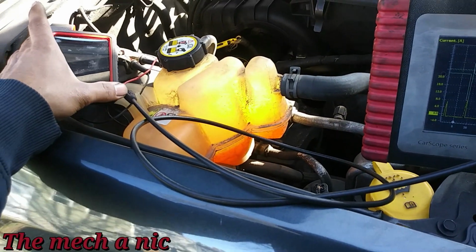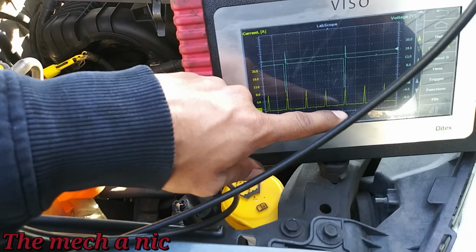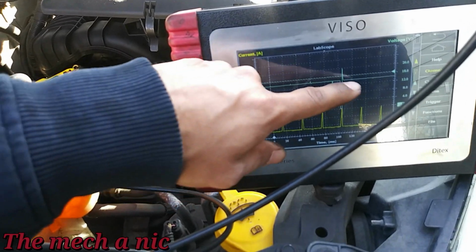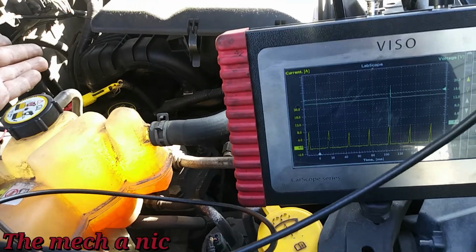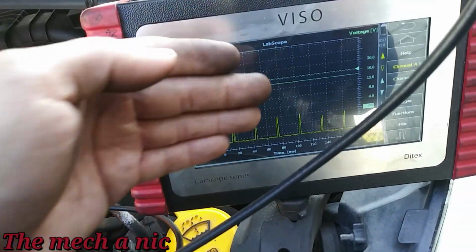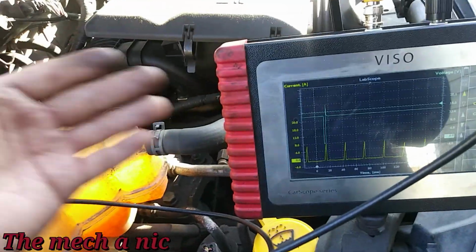One thing I overlooked is if we disable injector number 4, not only are we going to lose our waveform for channel 1, which is the current, we're also going to lose our waveform on channel 2 because we're disabling the injector, so there's no open time, if that makes sense. So you would just lose both of them, and that's how you would know that you're on the correct wire